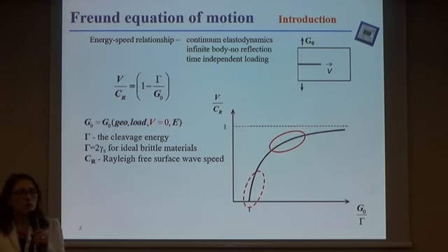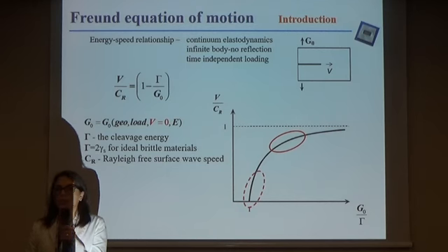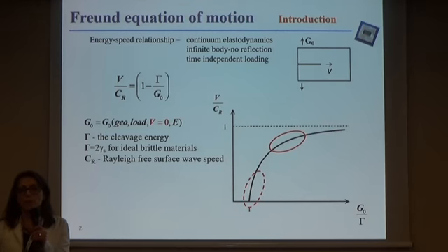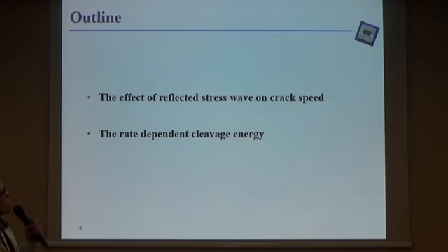So we postulate that if we build the energy-speed relationship from our experiments and compare it to the Freund equation of motion, each deviation should point to an energy dissipative mechanism that could be the effect of reflective stress wave on the crack speed. I would also like to share with you my latest results on the rate-dependent cleavage energy.